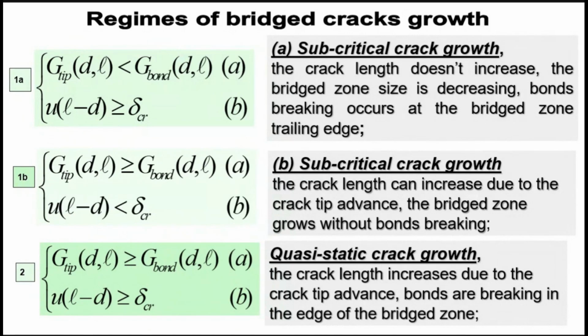In the regime of quasi-static crack growth, the crack length increases due to crack tip advance, and bonds are breaking at the edge of the bridged zone. Next, please.